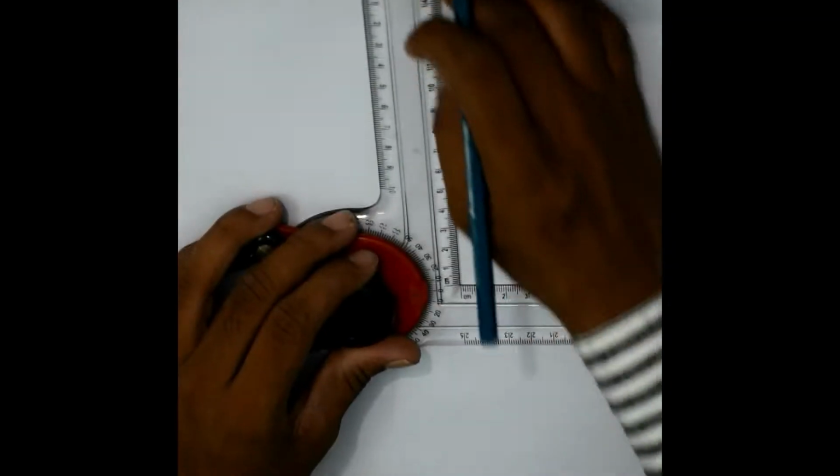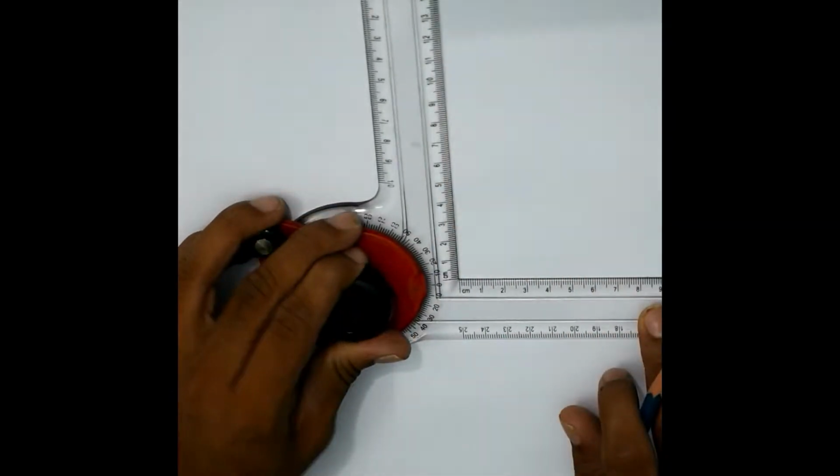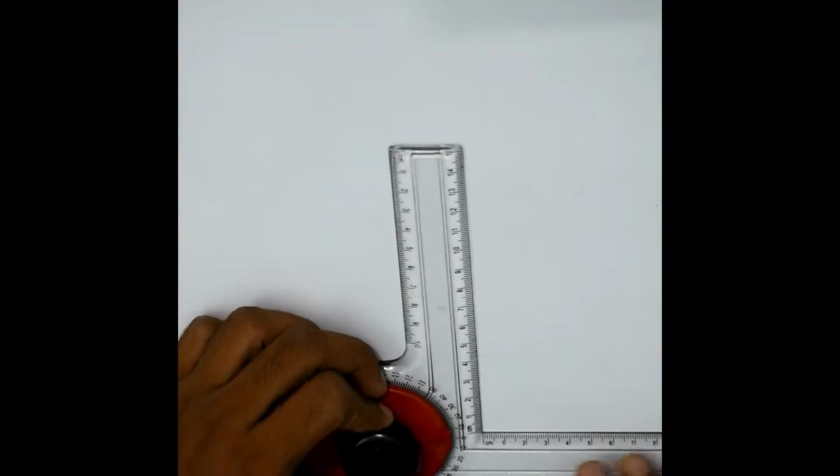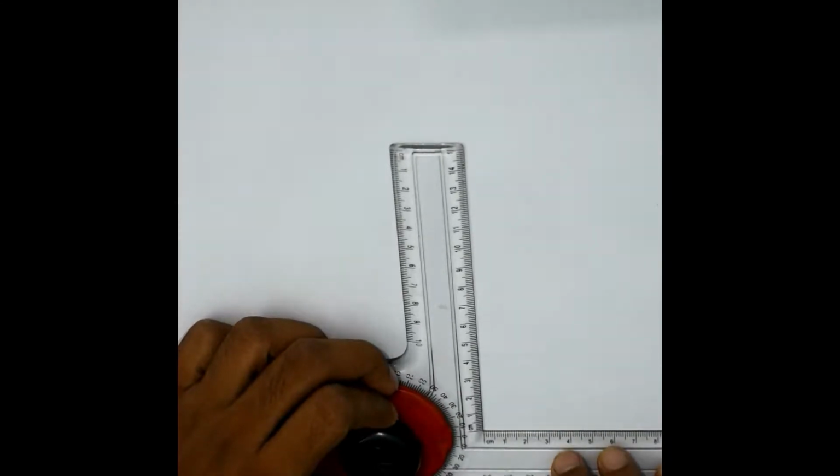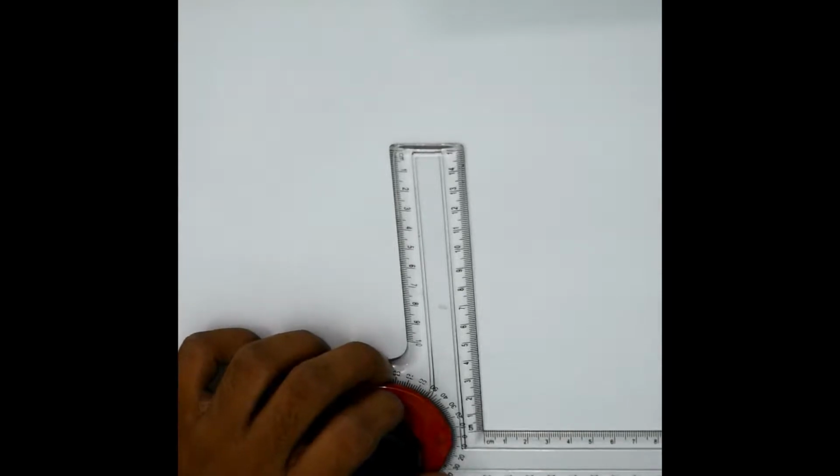So as this is a square pyramid, first we will draw the projections of a square pyramid, and I will use first H pencil because as this is a question of section planes, the main answer will be after sectioning. So for drawing this square pyramid, side 40 mm and axis 70 mm is given, and it's resting on the HP.